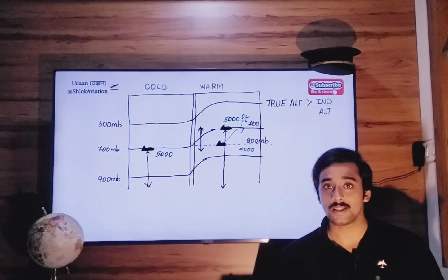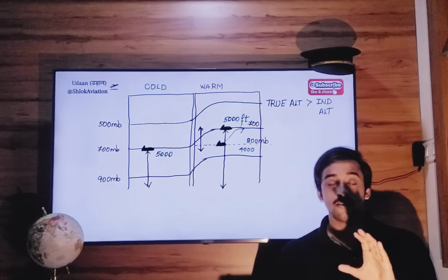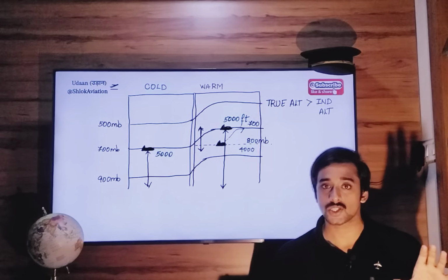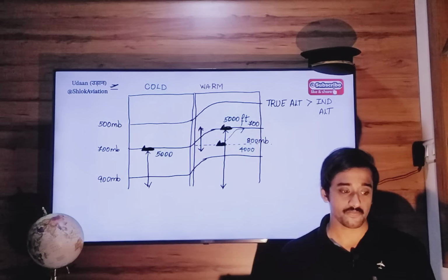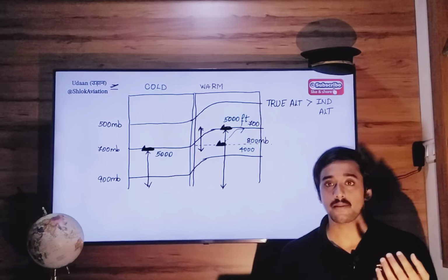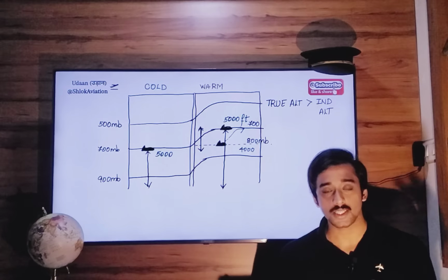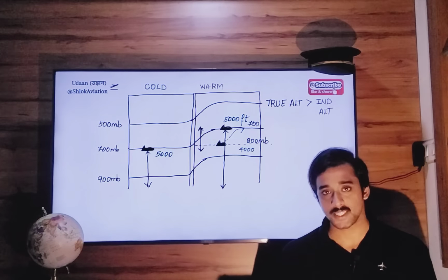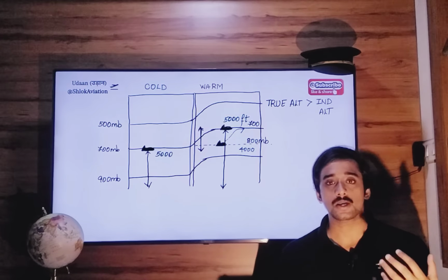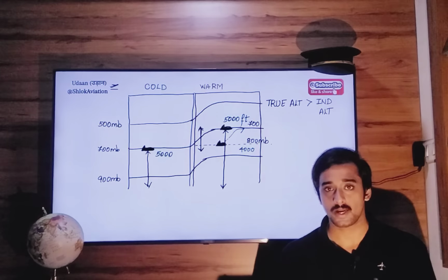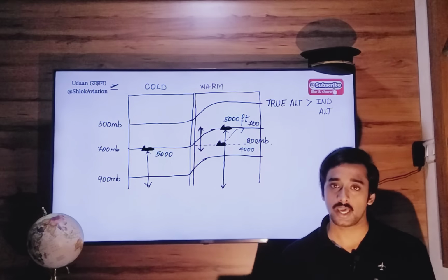What is the solution when you travel to different places and encounter different temperatures and pressures? Keep updating your altimeter pressure setting window. Keep updating your QNH, so this error will not happen. Now this error is called temperature error.